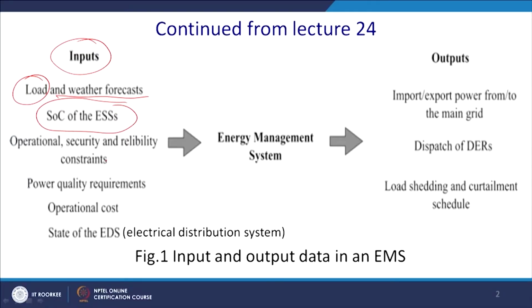So, you want to have some kind of SOC before that you can switch on to maybe the load shedding mode or shut down the non critical mode. And of course, you require to have a power quality requirement, like you want to make it a PQ control, and you should inject power at unity power factor with a very low THD, and also the whole purpose would be to reduce the operational costs, and thus by the